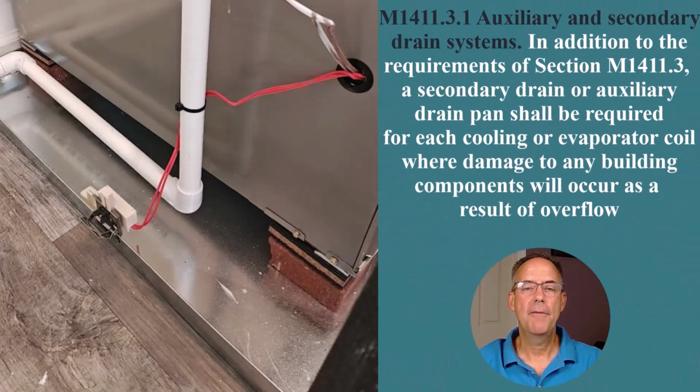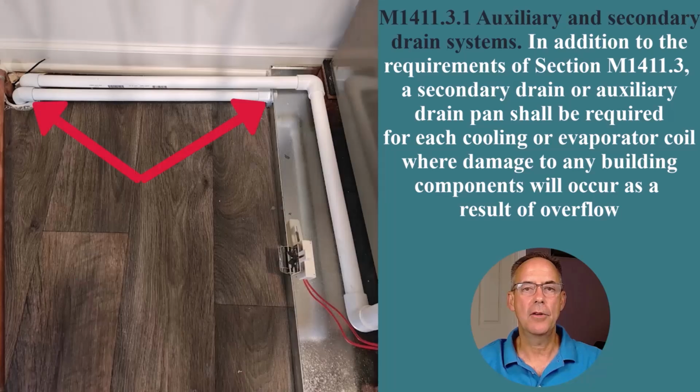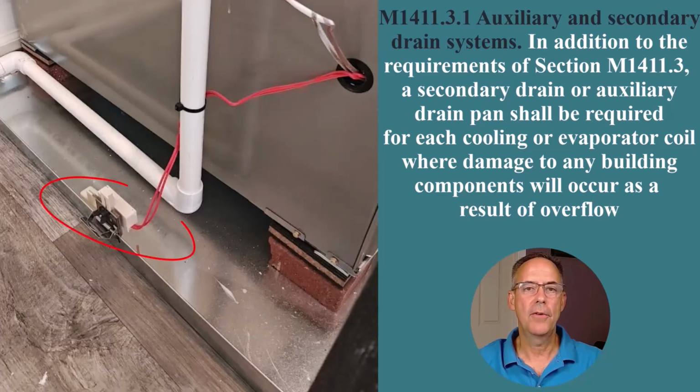Section M1411.3.1 of the mechanical code also tells us that if a unit is placed on the second floor, in an attic, somewhere where it's not seen, or where there wouldn't be a conspicuous area where you would be able to see if the pan was overflowing, you're going to need a pan on the unit, and you're going to need an auxiliary or secondary drain. And that's if you can actually see it draining. If not, if it's somewhere where you're not really going to see it, you need to have some type of a shutoff, so that if the pan started to overflow, it would shut the unit down and somebody would go and check on it and know that there was some type of a problem.